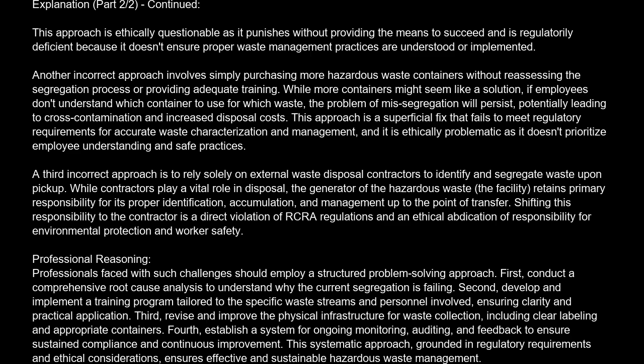A third incorrect approach is to rely solely on external waste disposal contractors to identify and segregate waste upon pickup. While contractors play a vital role in disposal, the generator of the hazardous waste, the facility, retains primary responsibility for its proper identification, accumulation, and management up to the point of transfer. Shifting this responsibility to the contractor is a direct violation of RCRA regulations and an ethical abdication of responsibility for environmental protection and worker safety.